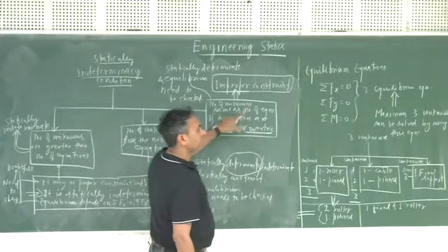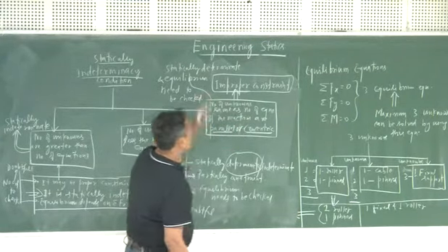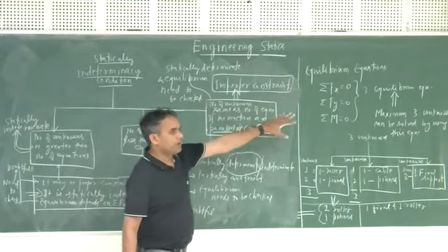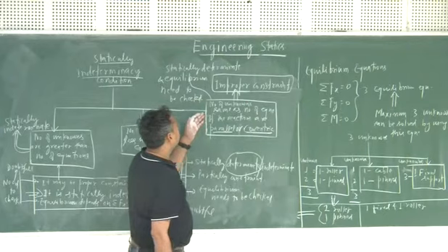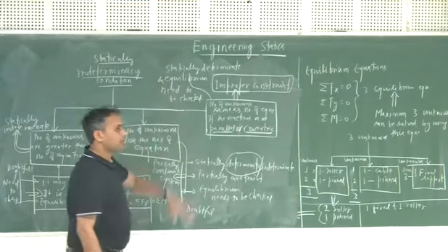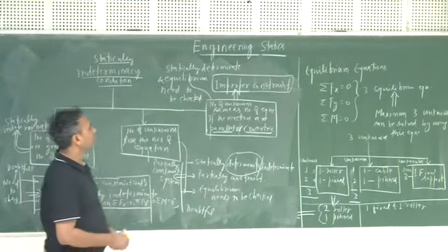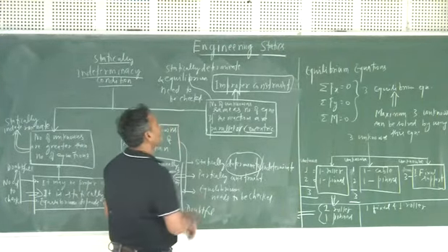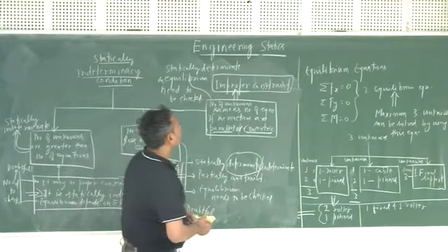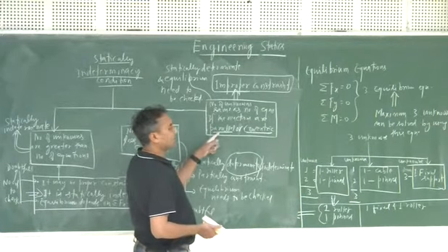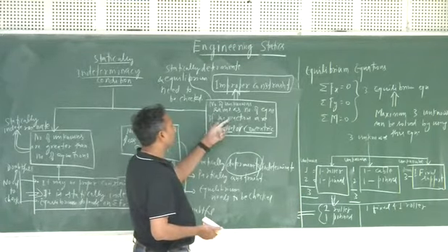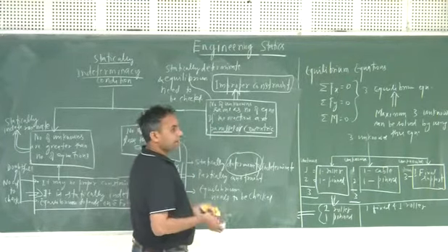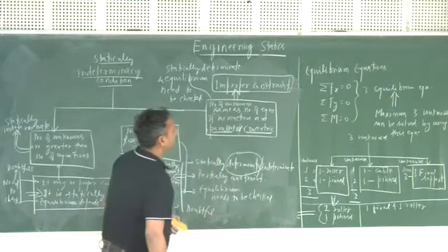When unknowns are the same as the number of equations, it means you are almost satisfying the requirement where three unknowns are required. So it may be statically determinate or indeterminate, and provided the equilibrium equations are satisfied, it will be statically determinate. But if the reactions are provided such that they are parallel or concentric at a point, then they are called improper constraint systems.